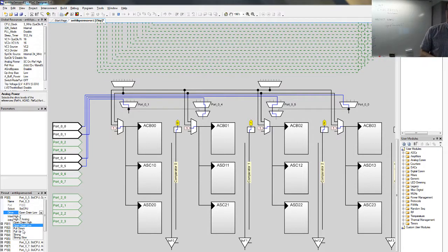Or, okay, if this was an I2C device, basically you can do low speed I2C without external components by making it a pull up, and then tweaking a little bit with more code while you're actually driving the line. But anyways, it can be done.